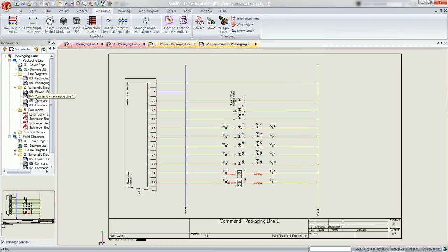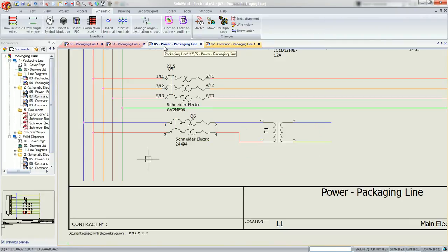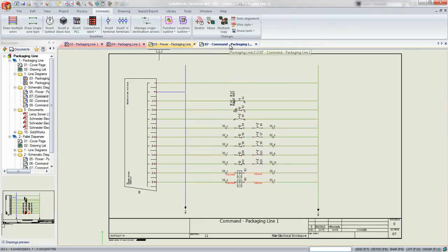With large electrical designs, the use of multiple pages for the schematic is a standard engineering practice. To maintain electrical connectivity and create a continuity link between circuits on different schematic pages, off-page circuit references are used. In the case of our example, the output of the transformer circuit needs to be linked to the PLC power input circuit on a different schematic page.